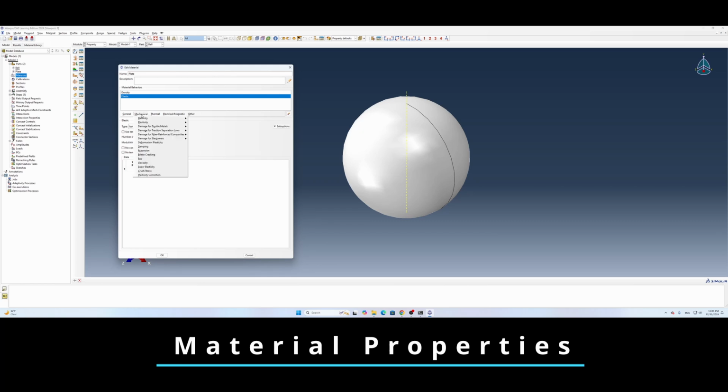So we got the elastic, and then we need to do the plastic. For the plastic, I'm going to use this number. The maximum plastic strain is 0.5 here. Then we have to define the material failure criteria. To do that, we go to mechanical, the damage for ductile material, and then the fracture strain. The fracture strain happens after the maximum plastic strain. The maximum plastic strain is 0.5, so that's why in here I'm going to use 0.6.